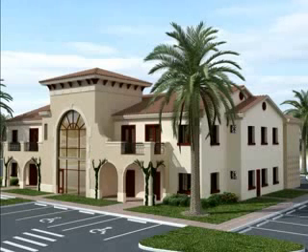So make sure you separate your objects and apply displacement to the objects in the foreground when necessary, and not to objects in the background. And make sure you use displacement where it's really needed, i.e. don't add displacement to something like a brick wall unless the brick wall is close enough to justify it. Use displacement wisely or it will increase your render times unnecessarily.